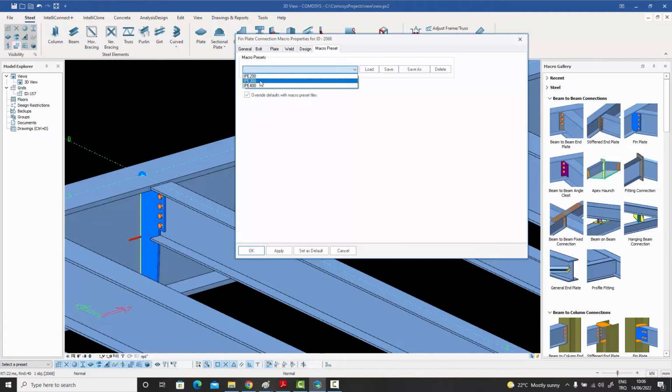If you consider all the possible sizes of beams, the IPE sections, INP sections, UPE sections, HEA, HEB, all of them are possible situations, and each one of them probably has about 20, 30 different section sizes. So what is right now quite manageable on the screen, if I were to actually enter my company standards for all the possible sections which we use in our day-to-day detailing, then this list will actually become a nightmare.